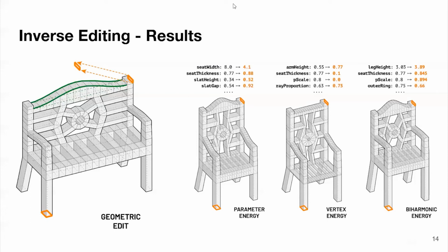And this is because it's trying to keep those vertices lower, right? As we make the overall model higher, the vertices that were previously on the seat and top of the chair want to stay closer physically to where they are, regardless of the global context of the model. And so it ends up making these somewhat strange deformations. If we use, say, the biharmonic energy, which preserves the kind of local transformations, we end up getting a much better result. That really preserves the global overall structure of the chair, such that it resembles the original bench, but now contains the desired form.